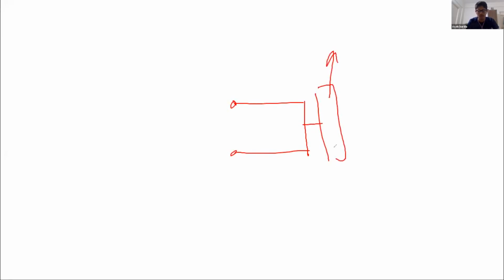If your wheel is just moving up and down, you can say that the camber is zero continuously, right? So this is the position when your wheel has gone up by whatever amount. Your links are parallel to each other, they are of equal length. So they produce no adverse camber during just bounce or rebound. During just translational motion, you have no camber at all, and this is very good, right?